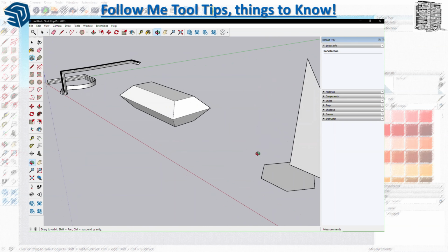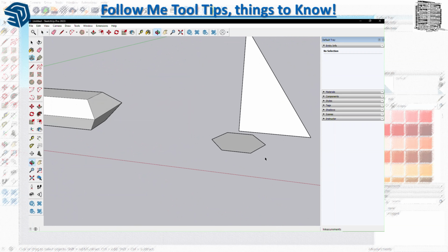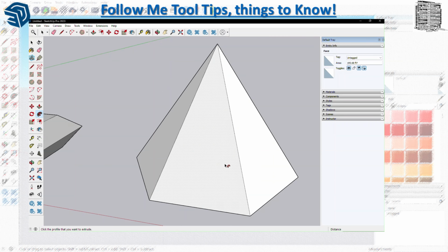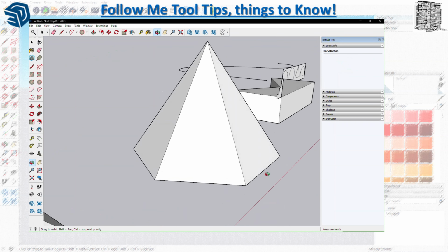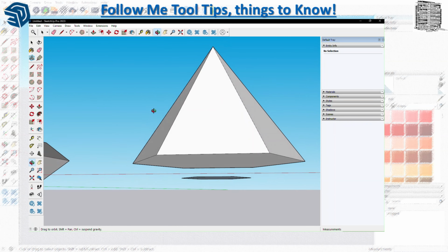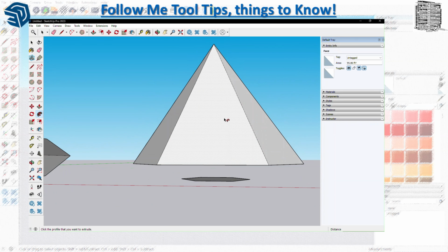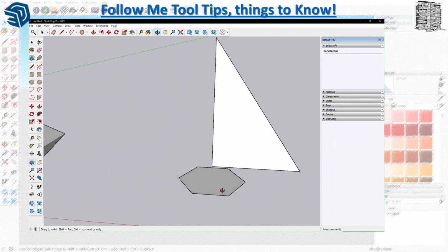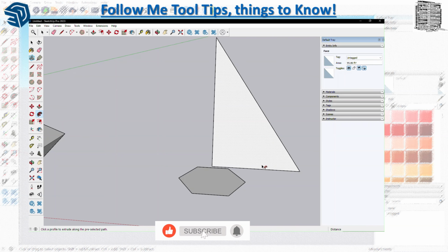You can also use Follow Me to create more complex objects. Right now we have, let's say, a rectangle, a triangle shape, and a polygon. You can select, and you can see how easily, without even connecting those two shapes together, you can create complex shapes, right? You simply click on the object, Follow Me, click on the base that you want, and it's going to follow the shape that you need.